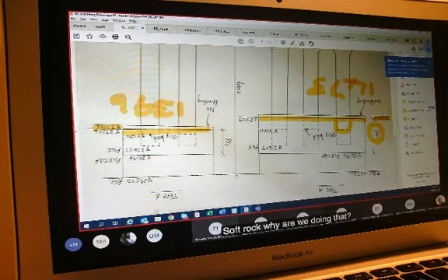We also have to measure extra over back excavation for working space for excavation in soft rock. Why are we doing that? Because our instructions say that everything we do when it deals with excavation, we have to allow 10% for excavating in soft rock and 5% for excavating in hard rock.